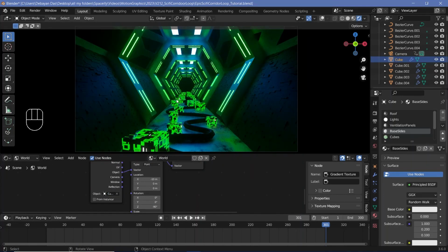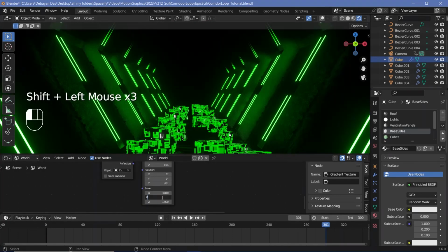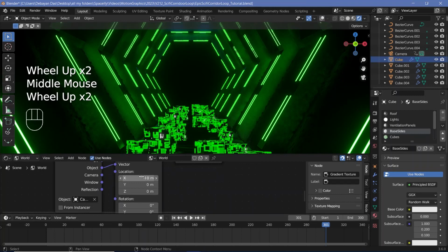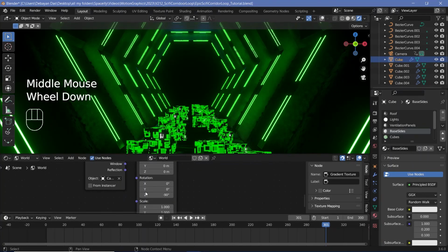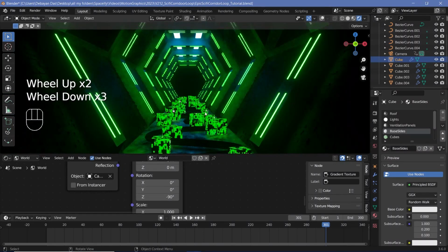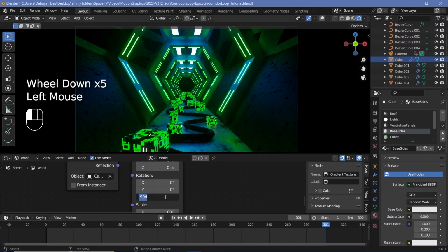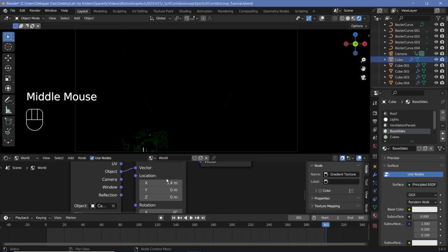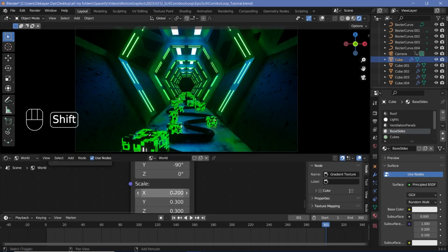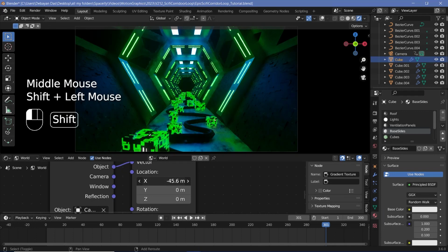Now the actual volume moves away as the camera moves away as well. And now between 0 and 300 we can take a look, and we might have to play around with the location and the rotations and things like that, because now we're using the camera coordinates and not the generated coordinates. In this case, I think the Z value was the wrong rotation. So yes, we had to rotate it on the Y axis by minus 90 degrees and then push it on the X and scale it on the Z, after which we can play around with the X location to bring it in and bring it out.